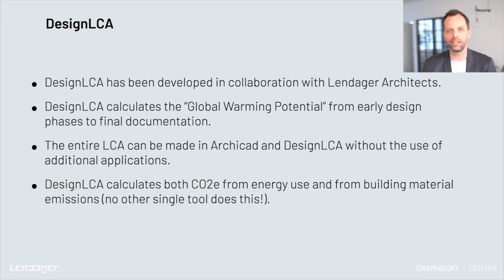And I've written on the slide, no other tool does this. So we haven't found a tool where you, without jumping to another application, without entering information from other applications, can calculate a complete LCA calculation with both material CO2 and operational CO2. And the reason that we can do this is because we have EcoDesigner Star inside Archicad.